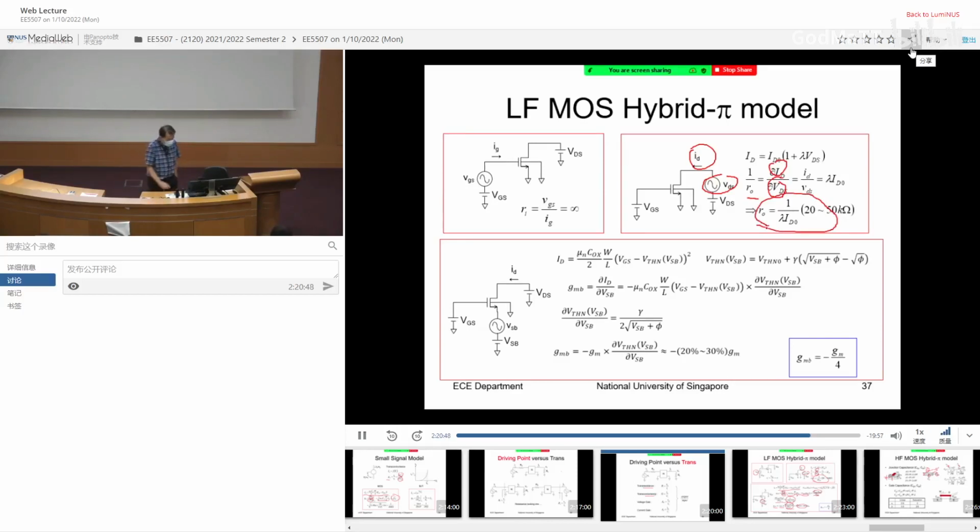Now, MOSFET is a 4-terminal device. So besides changing the gate, we can also change the source-body voltage. By changing that, I can also change the current. Not a preferred way, but unintentionally, you can do that. Okay, so in some research paper publications, people run out of ideas, so they would come up with a circuit originally controlled with the gate. They will say, oh, let's do it using the body. The idea is different, but it's actually a poor idea. Okay, because it's never a good control. So you can see some research publications doing that.